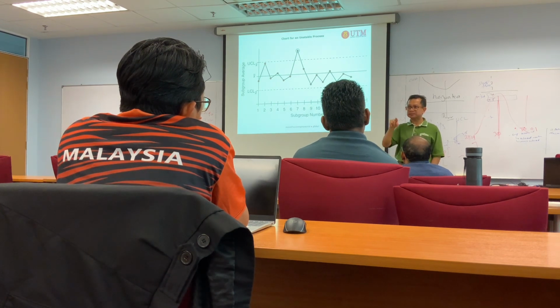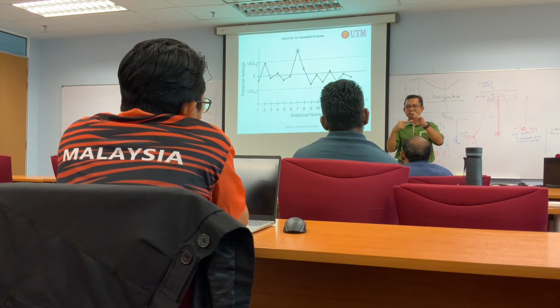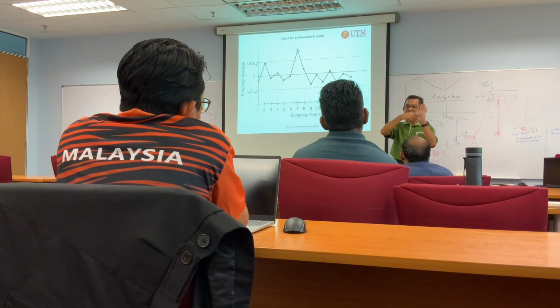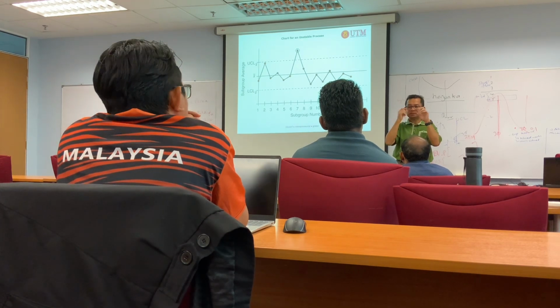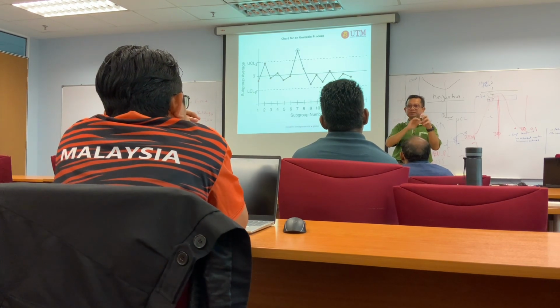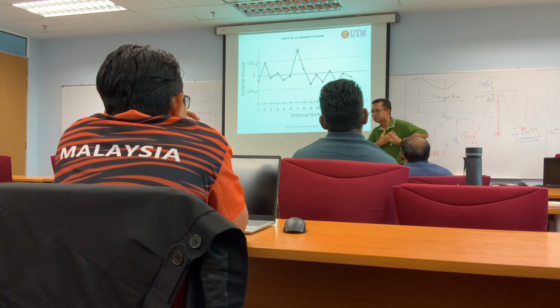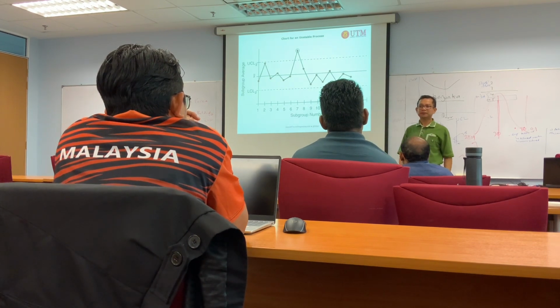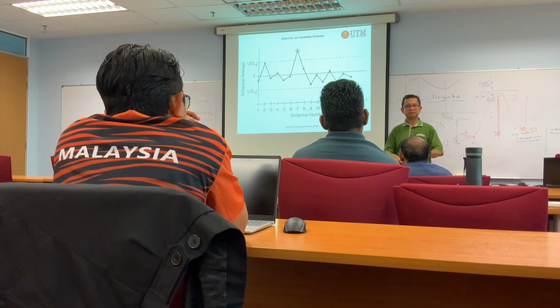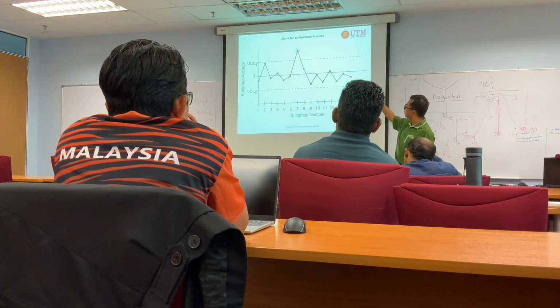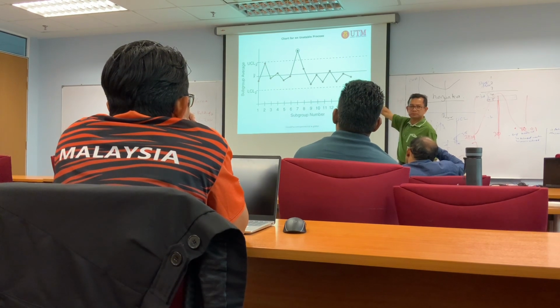And finally they realized the design has a curve stress concentration. When you cut, you should allow the curve so that the stress will be distributed. Because of stress concentration, they had to destroy the entire lot of the crankshaft. And it is history in Toyota. It happened in Toyota when they received complaints about the propeller shaft. So for this one, we have to remove the entire lot actually.